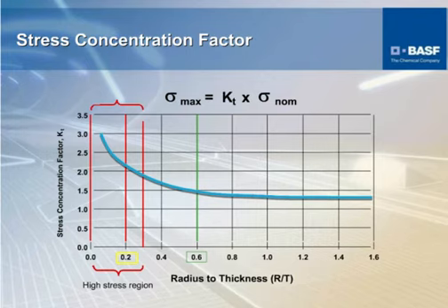This is a stress concentration factor curve. And you can see here from this curve, and this is why we've picked 60%, that the curve starts to level off. When you do your design calculations and you don't include a stress concentration, which most people don't, you're assuming your stress concentration is 1. In reality, it's going to be a little bit higher than that, but if you have a sharp corner, say you're in this high stress area, if a sharp corner could be less than 0.1 even, what your calculation tells you, you're going to have to probably multiply by 3 or even more.